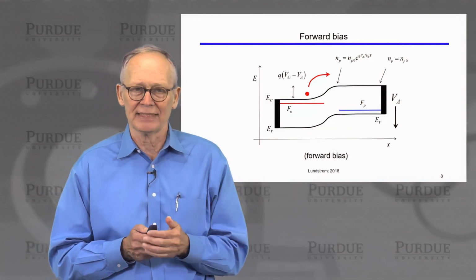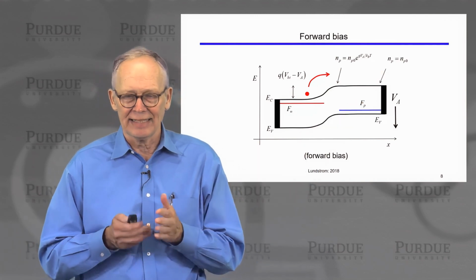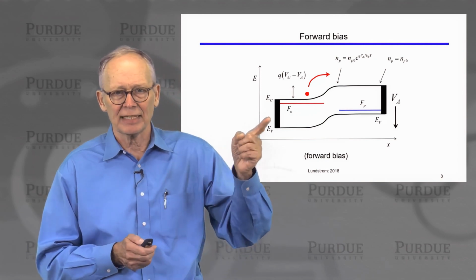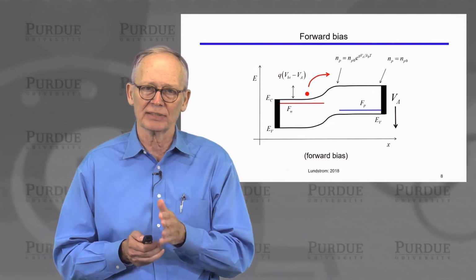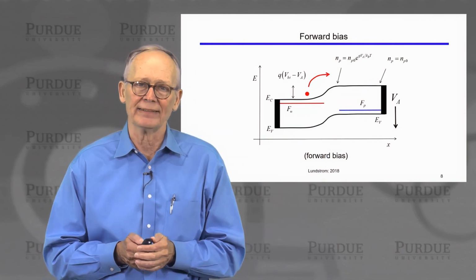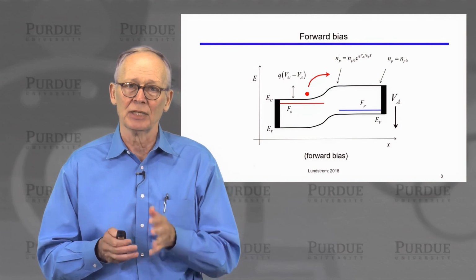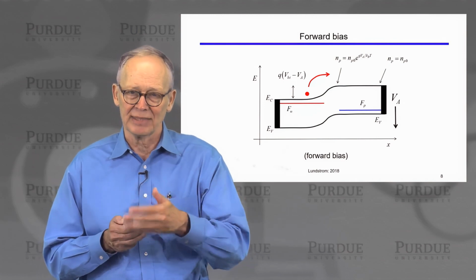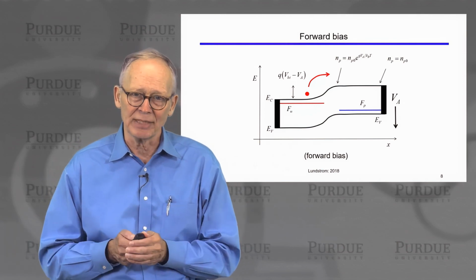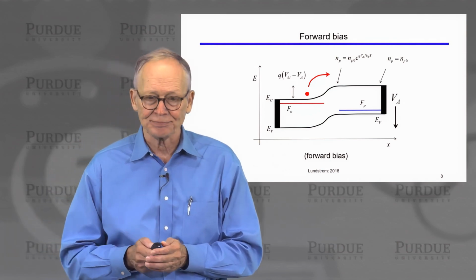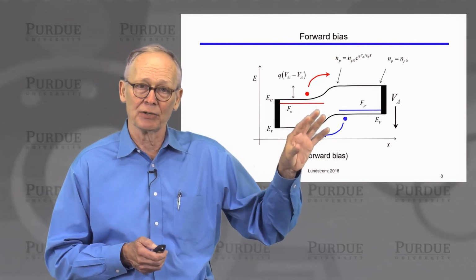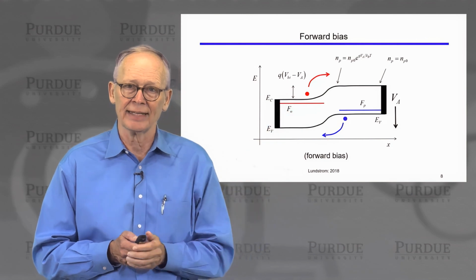And we will assume that the ohmic contact has a property where it's a highly defective surface. Any minority carrier electron that reaches that surface immediately recombines. So we will always maintain the equilibrium concentration there. We can't get away from equilibrium because the excess electrons that have been injected recombine immediately when they hit that metal contact. Now, we have also lowered the barrier for hole injection into the n side.